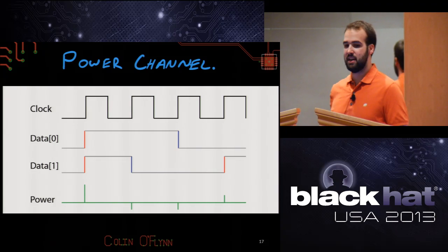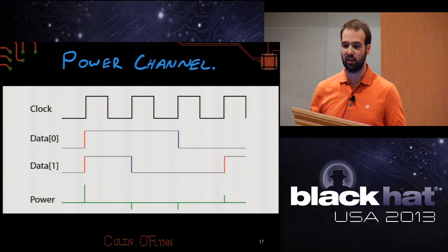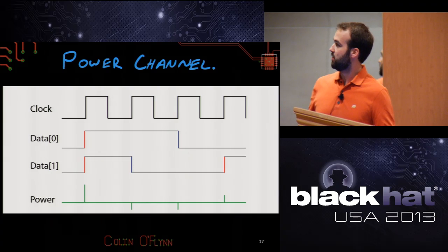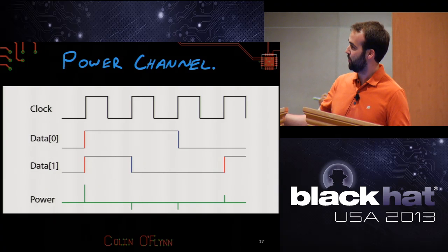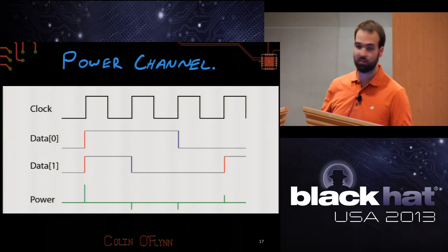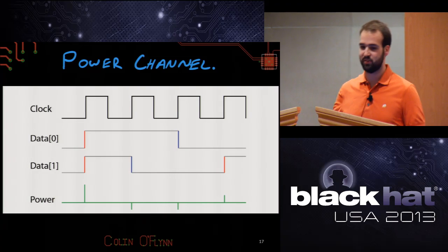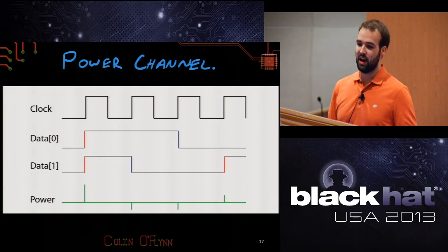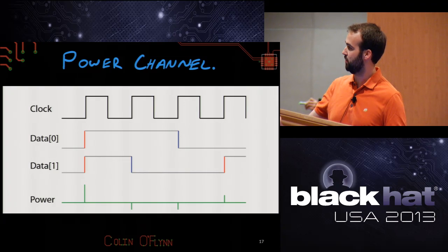Importantly, all of those data lines are switching at the same instant in time. They're switching relative to a clock. So we have a clock on the digital system, and you have the data lines. When that first clock edge happens here, 2 data lines switch. So on this side, first clock edge, 2 data lines switch, and there's a big positive spike, because 2 of the data lines are switching. At the next positive clock edge, only one of the data lines switches, and it's going from positive to negative, so we see a bit of a negative spike.